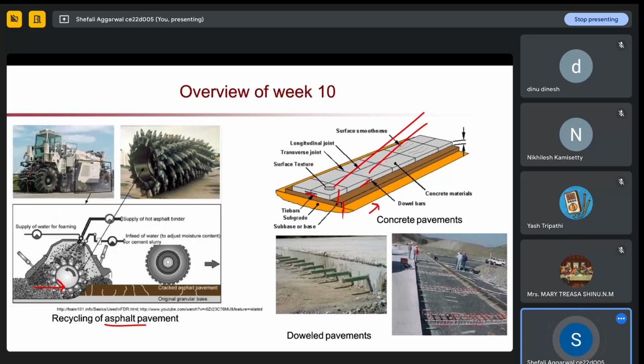If we talk about joints, in this case we have dowel bars. Wherever we provide joints, we will provide dowels. It is like a simple rod, provided in a straight way, as you can see in this example. Our concrete is laid in different areas like this, and this will provide an expansion joint between two slabs, slab one and slab two. Between two slabs along the wheel load, it will provide an expansion joint or contraction joint. That is a dowel bar.